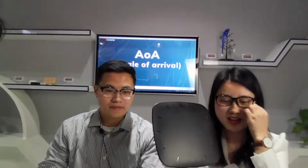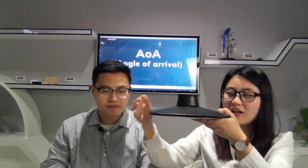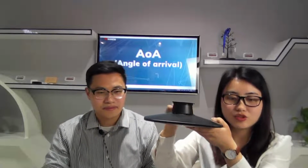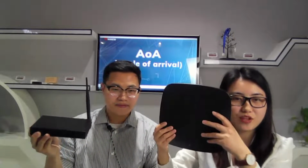I will start to introduce the locator first. So this is a locator. There are 12 antennas built in, as Ethan mentioned before. It's used to install on the ceiling and collect the data from AoA beacons, then send the data to the G2 gateway. So one set of AoA kit has 4 pieces of these locators.